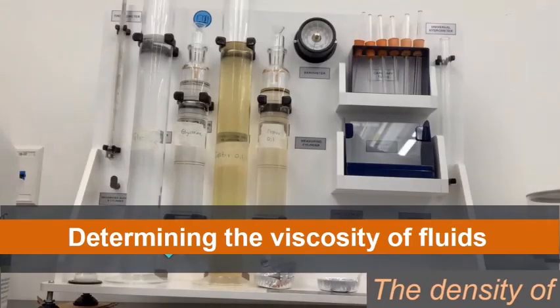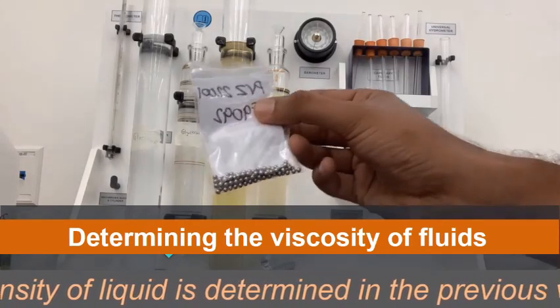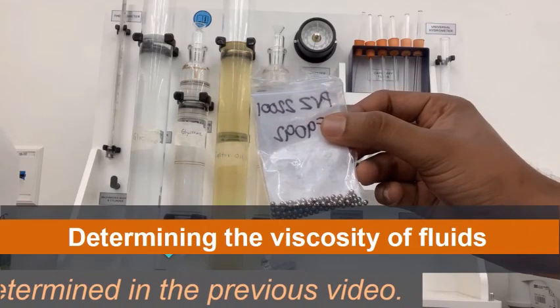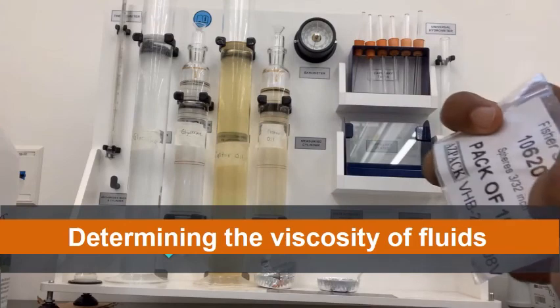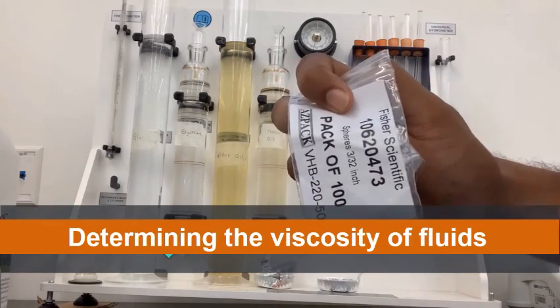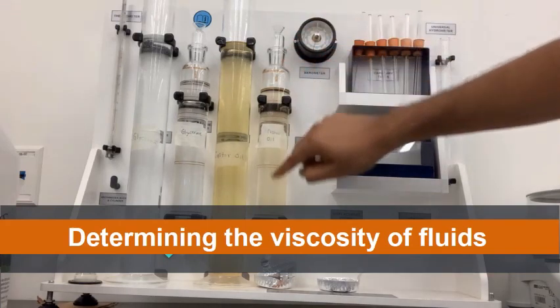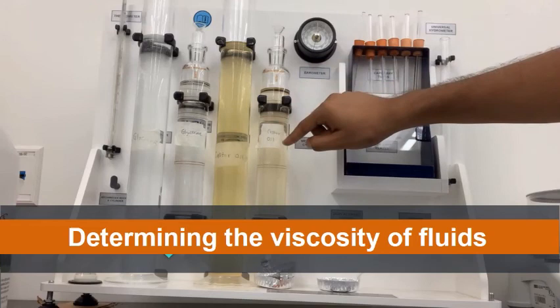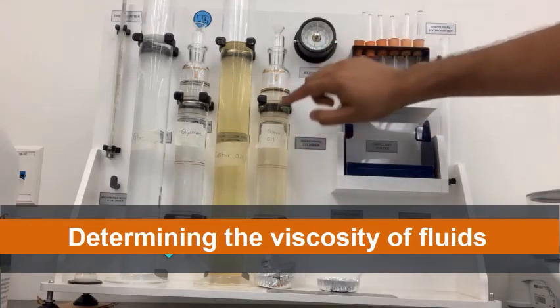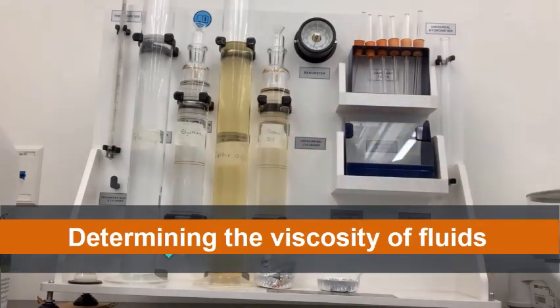And this procedure we'll just repeat for the other, different sizes or diameters of metal balls for each of the substances, for the castor oil and for the glycerin. Then we'll record the data, which we will use in our table to determine the viscosity of the substance.